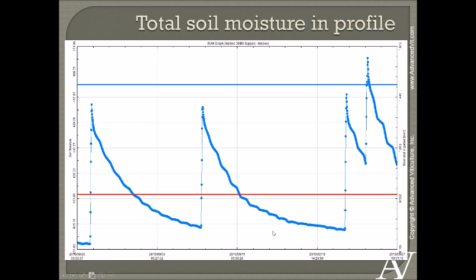So there's not a whole lot of water holding capacity, but you see initially that the vine's taking up moisture quickly, and then it slows down. What's happening over here is the vine is going into a stress, and it's closing its stomata and conserving moisture, and that's pretty interesting. But the other thing you'll notice here is that this gives us the ability to determine after an irrigation how long it took for that moisture to be returned to that same level, and that's really where the power of this device comes in. I can really know exactly how long it takes to deplete the moisture back to the same level.